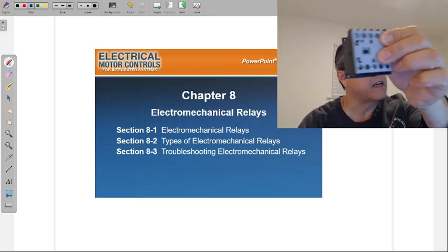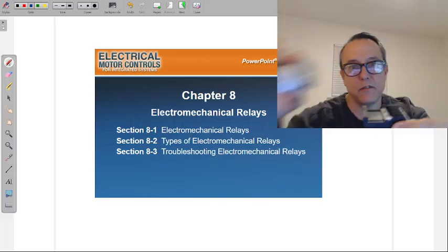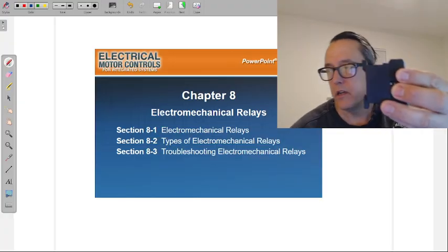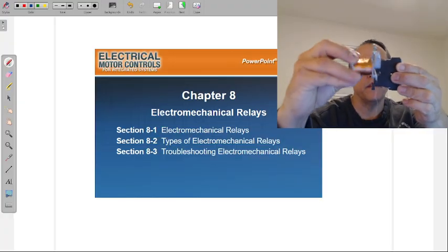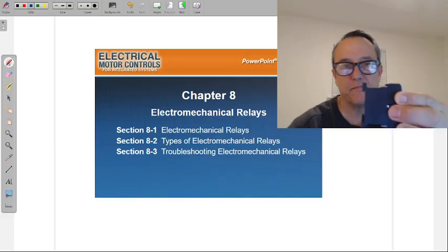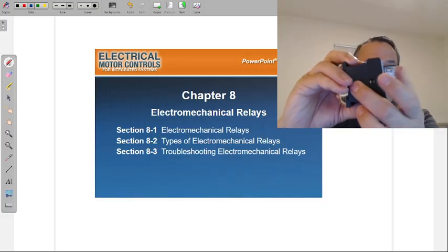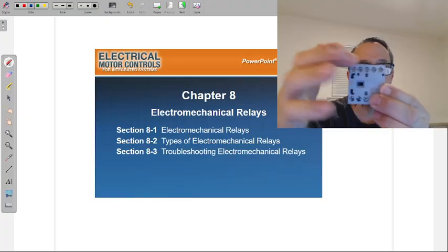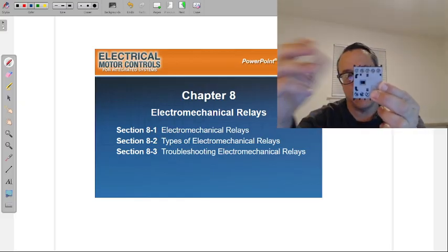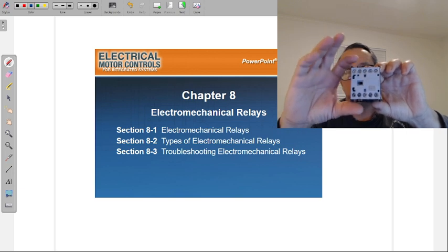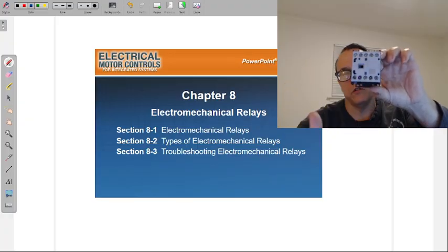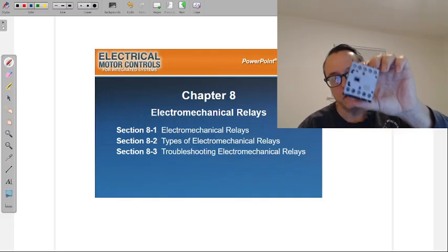So this is just a contactor, and you can't see it because it's not see-through like this one, but there's a coil in here, just like this coil that's here. As I showed you guys when I was showing you this, this is the coil that sits in there. Semi the same, sort of. And so when you energize that coil, you close these contacts here on the front, L1, L2, and L3. And in the world of three-phase, obviously online you guys aren't working with three-phase, it's DC, but same in operation. The three phases close and send power to our motor.